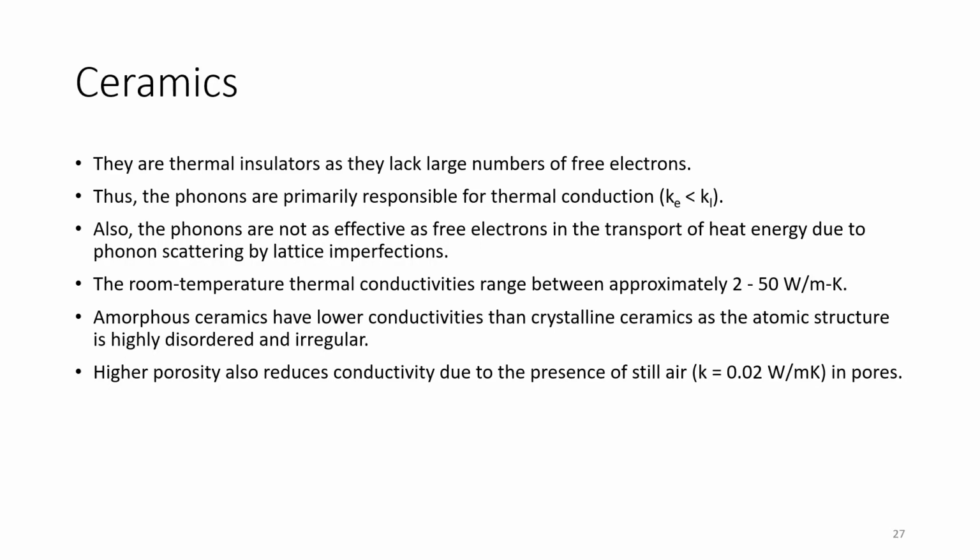Amorphous ceramics have lower conductivities than crystalline ceramics as the atomic structure is highly disordered and irregular. Higher porosity also reduces conductivity due to the presence of still air, because air in the form of pores has low conductivity, 0.02 watts per meter Kelvin.